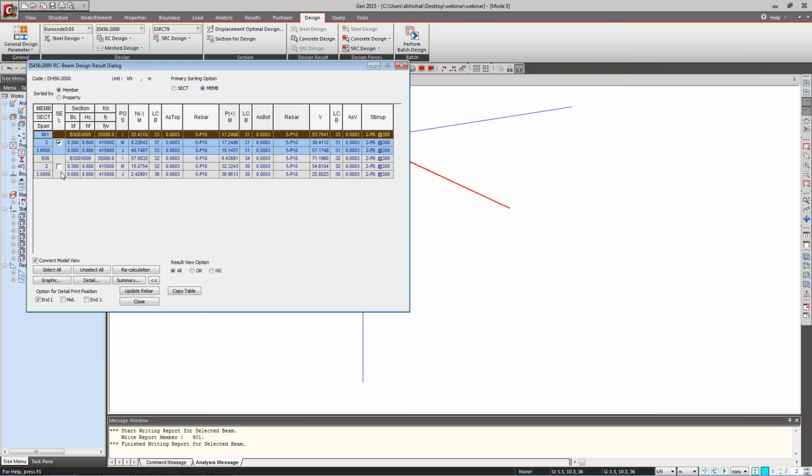And one more thing, we are using the panel zone effect. Mr. Ajit Gokhale sir is asking one question: are the bending moment values at the center or at a face in the graphics? It is according to the face of the member, not from the center, because we are using the panel zone effect, the rigid zone. That is my column and beam junction, a rigid area, so from that face I'm considering the moment. So we have to click the option called panel zone effect.